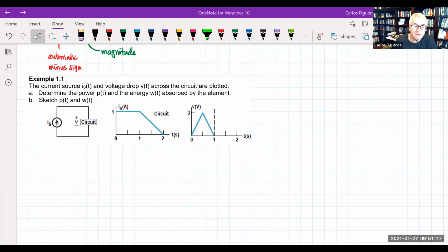If I say a current source, then it's not connected to anything. Sources are power supplies. They don't just put out voltage, and they don't just put out current. They put out both. So the appropriate thing to say is that this current source is a power supply that puts out a constant current. When I say I have a voltage source, I could say that I have a power supply that puts out a constant voltage. Those are details that I'm just going to have to beat the hell out of you with until you get them, because they're important details.